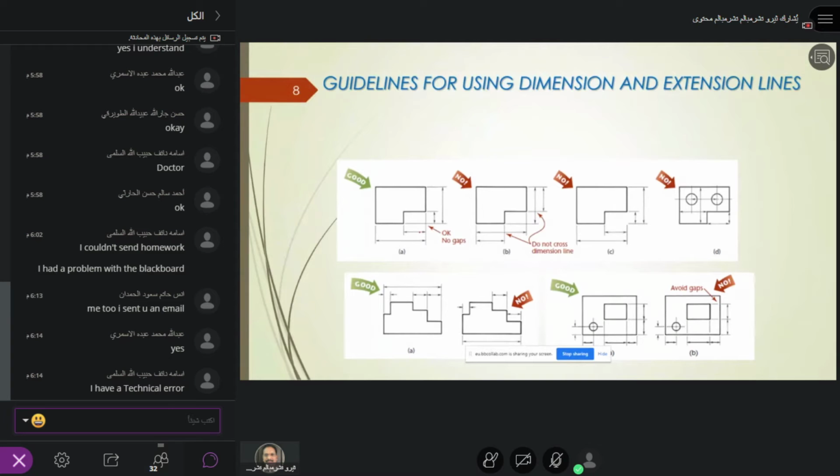Okay. This is good, but the extension line should not cross the dimension line. If you draw this line cutting it, you cannot mention the dimension here, right? So you should never allow an extension line and a dimension line to cut each other.